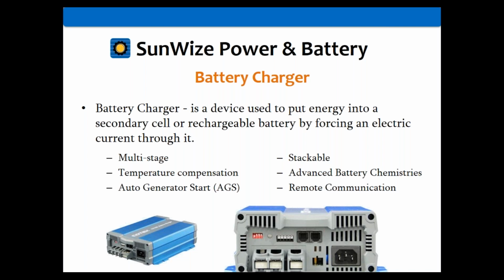And we've talked about this a lot with the PV chargers, but it also applies to the AC ones as well. Whether you have a bulk charge, absorption time, and then a float voltage, it may also have an equalize with it. Okay, you've also got temperature compensation, which is also very important. We've covered that multiple times in other webinars. And it may have some other things too. It may have some advanced logic to it for lithium-ion batteries or other batteries.